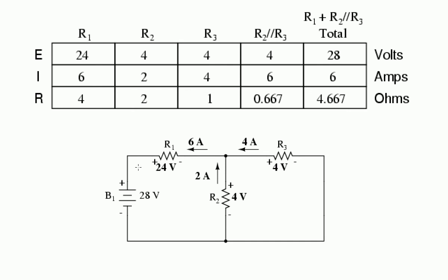So what have we got here? We've got 28 volts. We've got a current which is going through. So we calculate the current. And again, you can see it goes the opposite way around. We would say the current would go through here, then split up here, then some of it would go down here, and some of it would go down there. So anyway, we do Ohm's law, calculate all the currents, and then we put this into our table. And it's very, very important to remember which way the plus and the minus goes around for each resistor. Same here as well with the load. So they either are together or they subtract from one another. So very important.